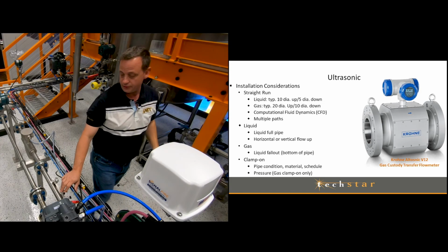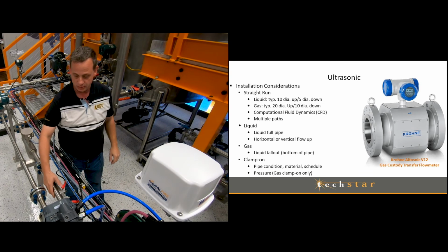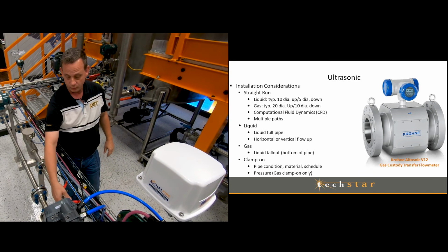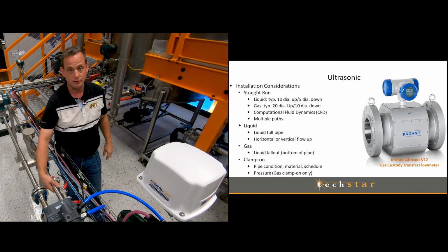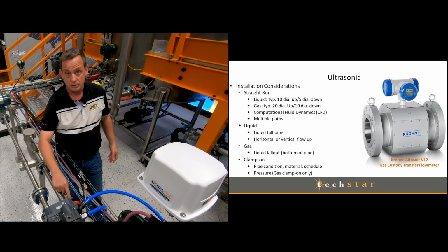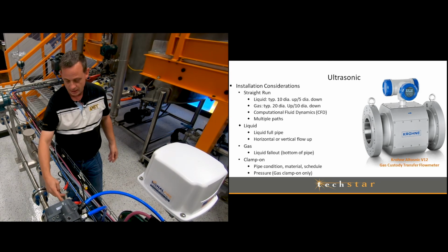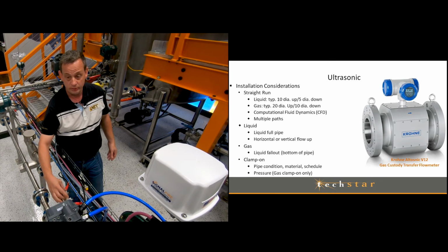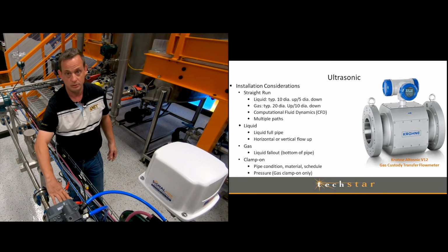There's also, for different size pipes or different installations, another example of an ultrasonic flow meter here. This ultrasonic flow meter is installed on the smaller size line, and basically the same thing. You can see that you have actual hash marks on the spacing, so you can space it directly reading off of what the holder says.